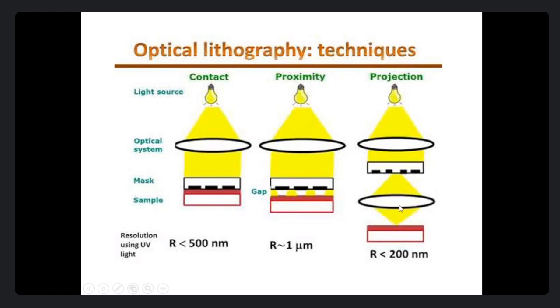Anyway, so the point is this lens, for the purpose of work that it is basically doing, is known as the refocusing lens, or you can say the most popular term people use is the projection or projectile lens. Basically it collects the light and projects or refocuses whatever it is onto the wafer. So it is also called the projector or the projecting lens. Yeah, this kind of terms.